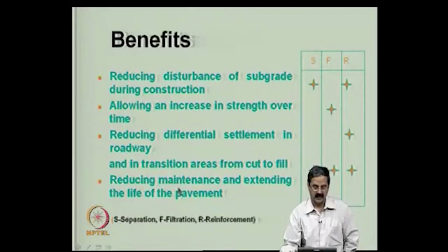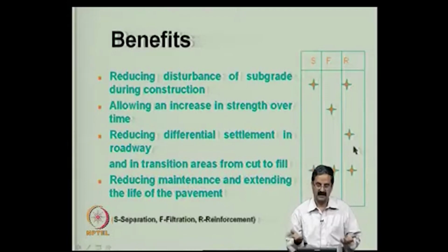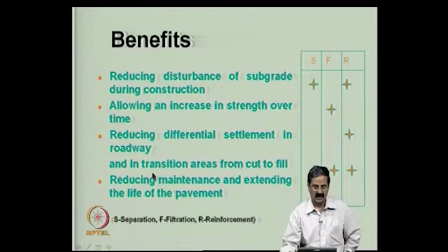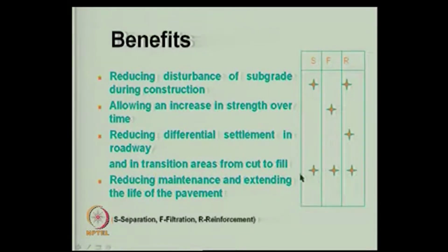Reducing the differential settlement, the reinforcement function helps, because that is one important thing in the transition areas from cut to fill. Again it helps. All the three things help. Reducing maintenance and extending the life of the pavement, all of these materials help in some sense, giving the benefit of performance, right.